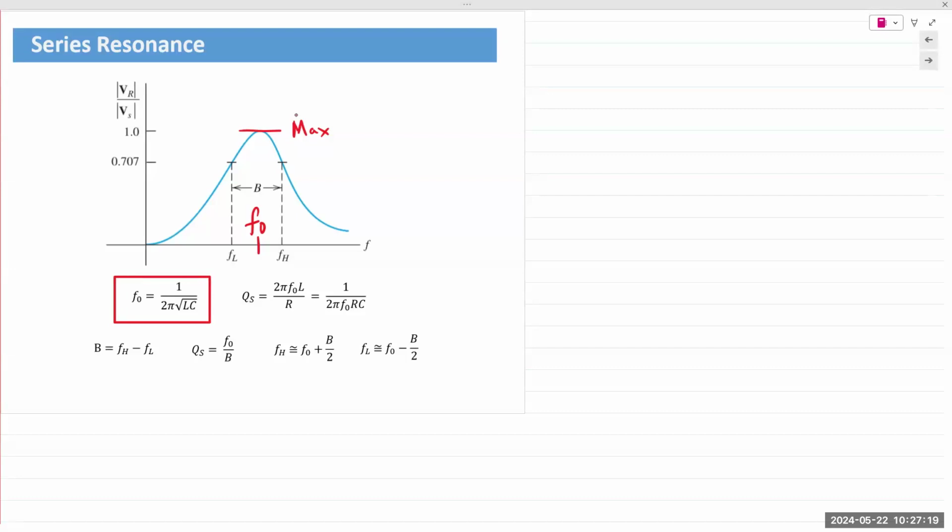So the question being asked is whether the goal is to run every filter device at its resonant frequency. It's yes and no, depending on the make and model. If you're talking about a real life application, money is always a consideration. If you use an inductor, you have to spend more money because inductors have resistance. So if you use an inductor in a filter circuit, it becomes very expensive because you need very high quality inductors so that the output is not lost in the inductor itself.